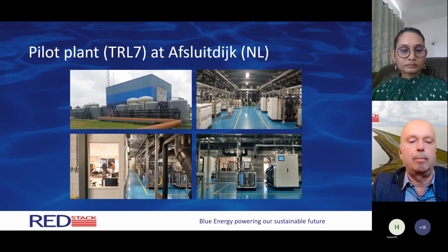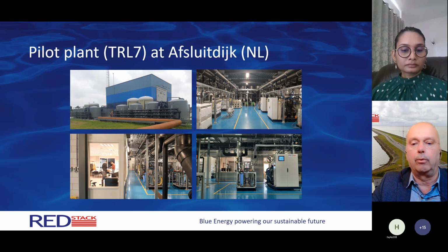Some looks inside the pilot plant. Left and top, you see the outside gray tanks. This is the pre-filtration system to remove the algae and sand and other stuff from the seawater and the fresh water. We don't want that in our membrane stacks, so we must remove it up front. And there are other pictures inside the pilot plant where we do test 8 different stacks at the same time, each fully equipped to have the salt and the freshwater mix and the pressure and the cross flow, counter flow, and so on to do all the development work.